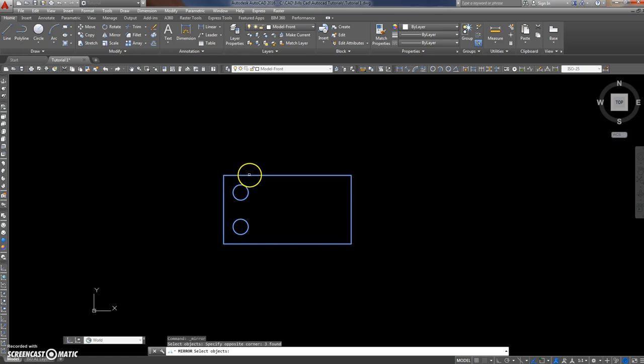If you want to remove that item from your selection, hold down Shift and just click on it. And that just leaves those two. So look down the bottom, mirror selected objects. We've done all our selection. We hit enter, and now we've still got no object snap going. But what if we turned it on? So we turned it on, and see how it locates to the midpoint.